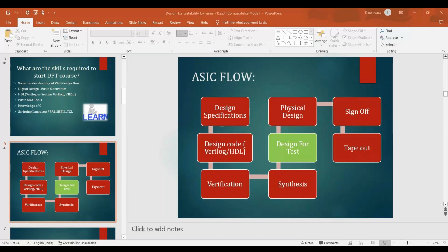In this course outline, there are many components which we are going to discuss. One of the first is the architecture of DFT. Architecture, in the sense, means what additional extra circuit you are going to add, and where the tool will be inserting it. You will not be inserting anything. There is a concept here called scan insertion, compression insertion, and OCC. OCC stands for how you control the clock, so it is called the clock control unit. This is also inserted by the tool again. We are not going to write the code for that.